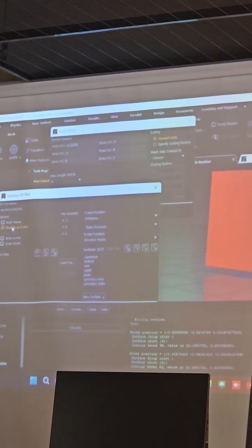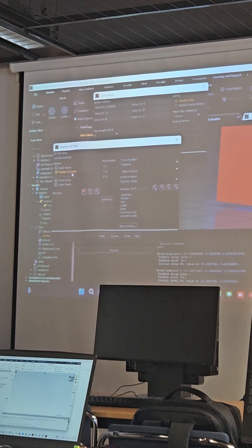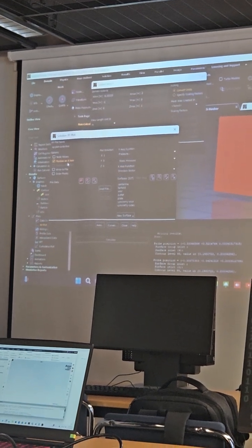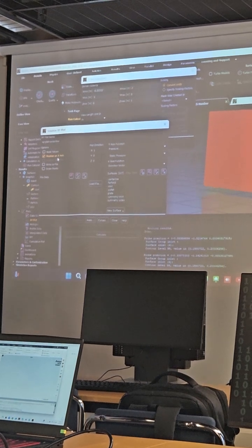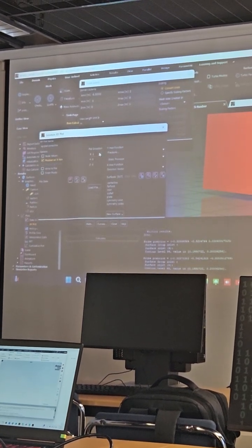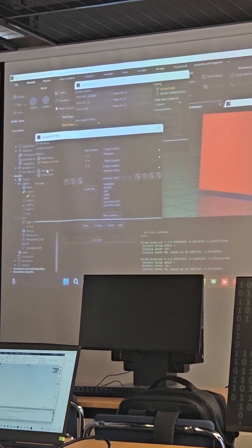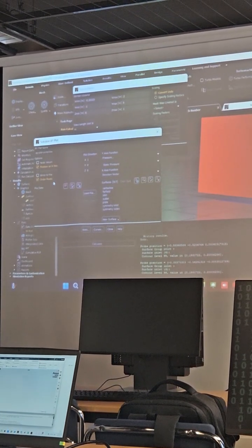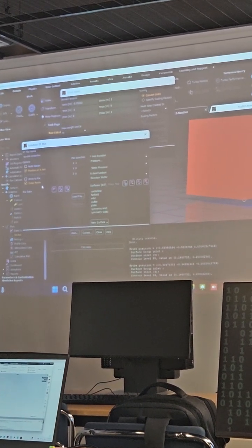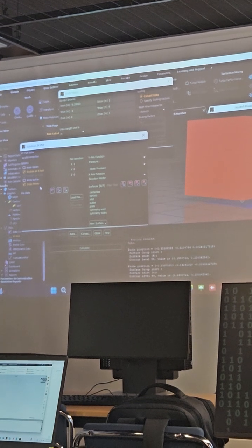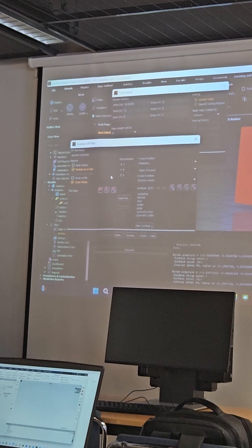And then the position on x-axis, we can keep that. This is asking you in which direction you want to plot your quantity. In our case, in the x direction, so that's okay. And then we can also order points. That means that the points will be ordered by the x coordinate, so we have an increasing x coordinate for each point, in case the solver is reading them in a different order.